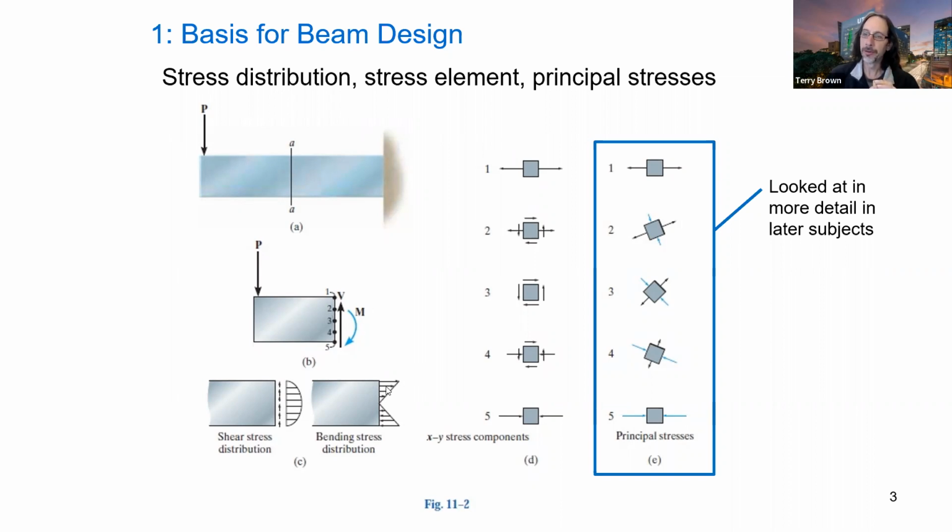So we'll have a normal stress, something less than the maximum, and a shear stress, something less than the maximum. Okay, so there's a combined stress here. It's equivalent to, if you're thinking about forces, you have a resultant force, and then you have the two components, force in the X, force in the Y. Here, what we're seeing is the stress components: a normal stress component and a shear stress component.